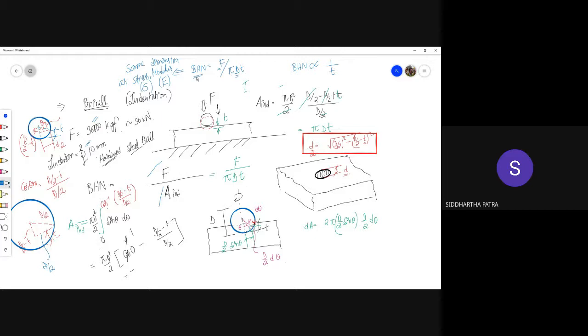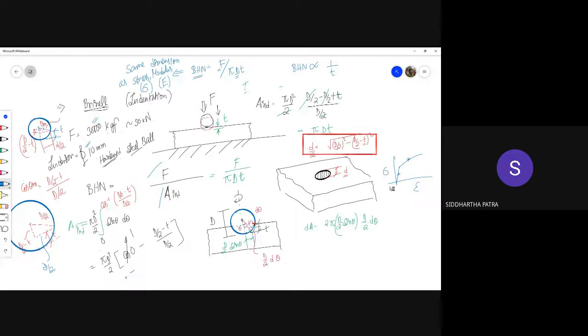So in reality, we earlier talked about bulk plastic deformation. Even in bulk plastic deformation, we talked about tangent modulus and Young's modulus in these two regions. And as we showed, that tangent modulus is approximately the hardness. So hardness is also a modulus where you are talking about resistance to plastic strain. So when you plot stress versus plastic strain, you have hardness as the modulus. So here also you see it turns out to be having the same dimension as modulus.